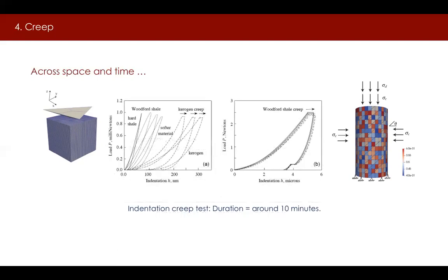We recall the standard loading protocol for indentation testing. First, the indenter is pushed into the surface of a sample. Then, the load is held fixed for several minutes before it is gradually removed. It is during this hold stage, under a condition of sustained load, where creep of the shale is observed. However, the hold period for indentation creep tests is limited to around 10 minutes, mainly because the measurements could be impacted by thermal drift, as well as by frame compliance, resulting in unreliable test data.